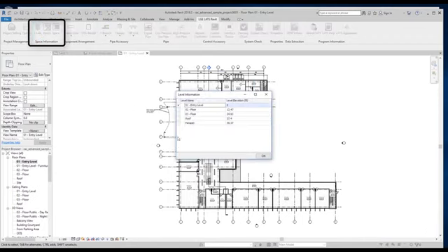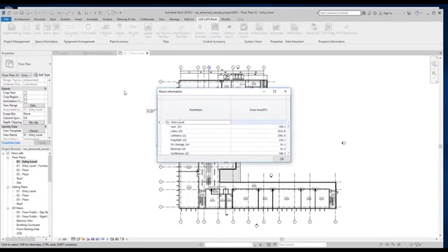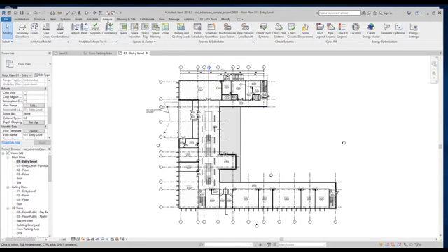Level, room, and space display information like elevation height, room area, as well as cooling and heating unit load. Level calculates the elevation and computation height of an entire level of the project. Room displays the area in each room. Automatically assign spaces to rooms in Revit.